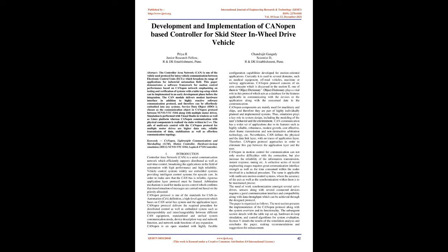The CAN module delivers a modest hardware interface in addition to a highly reactive software communication protocol, and therefore can be effortlessly embedded into any systems. Service Data Object, SDO, is chosen as the communication object in the CANopen protocol between NUVO-VTC 5104 along with multiple motor drives. Simulation is performed with Visual Studio in Windows as well as Linux platforms, whereas CANopen communication with physical components is realized via stubs written in C++.